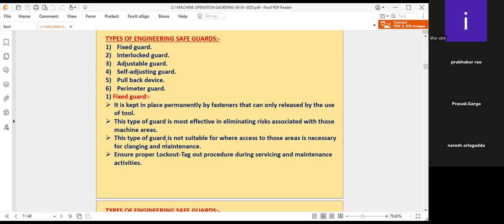In those holes the bolt, nut and washer will be fitted. Immediately, without the oxyacetylene flame and without cutting, they can simply use a spanner, and then you can remove the bolt, nut and washer. We can attempt cleaning and maintenance. The fixed guard is also sometimes not fixed with a bolt and nut. Some machines are permanently fitted, where the maintenance cannot be taken care of unless the guard is removed by welding or by cutting.